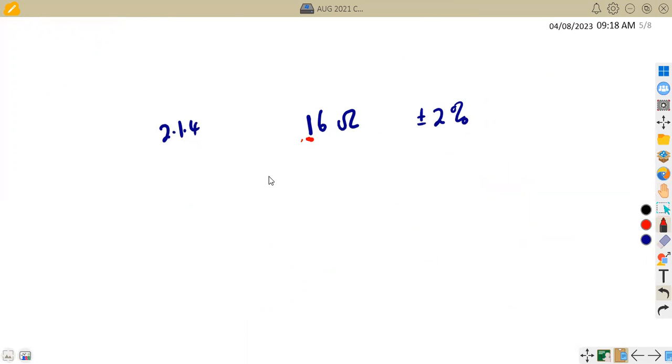We have black, brown, so this is going to be a brown in this case. Then 6, which is blue, remember digit, digit, so this is a blue, which is our digit. Then we are supposed to have the multiplier. In this case, we have 16 times 10 to the power of 0, which gives us a 1. So 16 times 1 gives us 16.